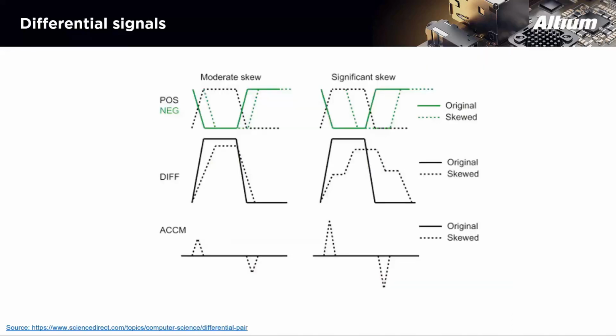Due to this nature, the two signals must arrive at the receiver at the same time. The receiver might allow some difference called skew, and the skew can be found in the chip data sheet. If we again unintentionally route these signals with different lengths, we add some skew and thereby shorten the margin given by the chip tolerance itself.